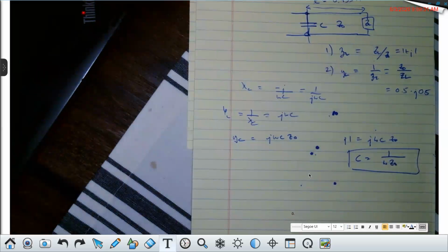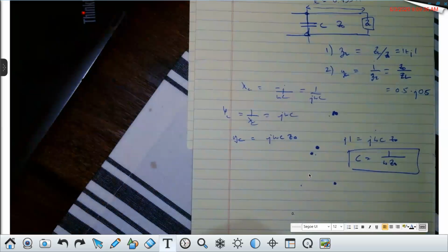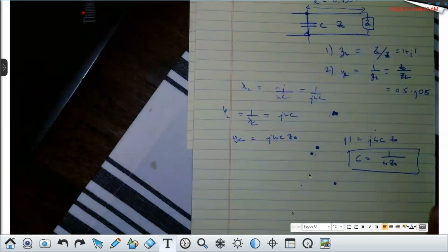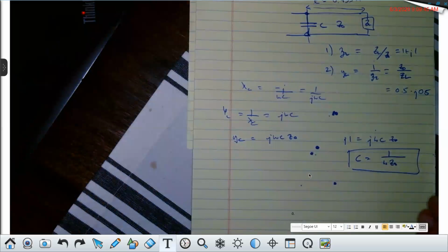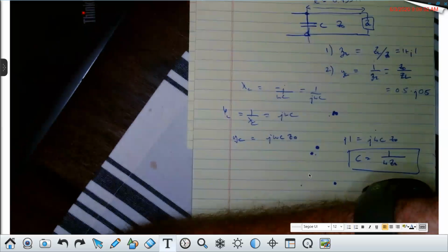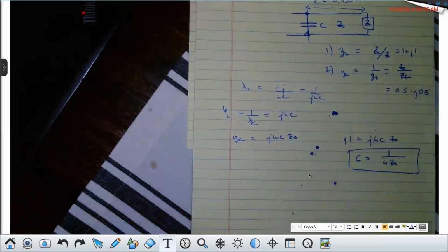Whenever you hear shunt, it means in parallel, and it's important you understand that. By the way, shunt stub or shunt tuning is used much more frequently than series tuning for a lot of reasons. With a shunt stub tuning, it doesn't have to take all the current through the line. If you put in a series inductor or series capacitor, all the current and signal goes through the component. This only takes a small fragment of that. You got me on that, class?